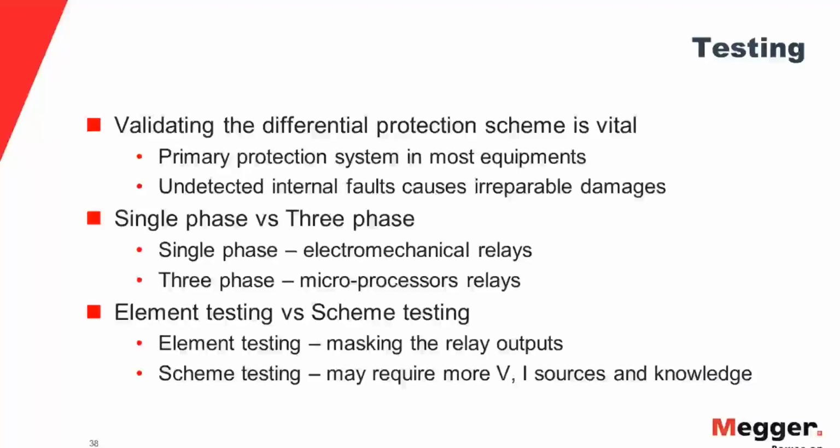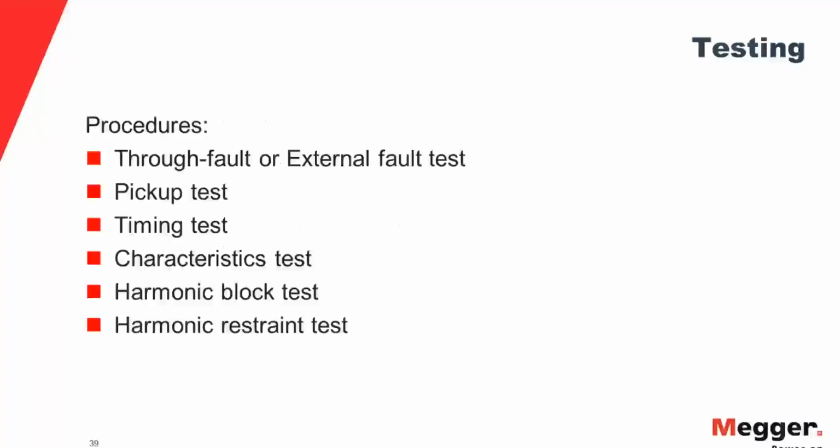So there are two things. One, do I do a single phase or three phase? Or do I do an element testing, or do I do a scheme testing? For single phase or three phase, if it is a microprocessor relay, depending upon the settings of the relay and the logic implemented in the relay, it is recommended to do what the logic dictates. If the logic dictates single phase testing or single phase tripping, then you test single phase. There is no harm in testing single phase. If it requires all three phases, then you need to have a three-phase system